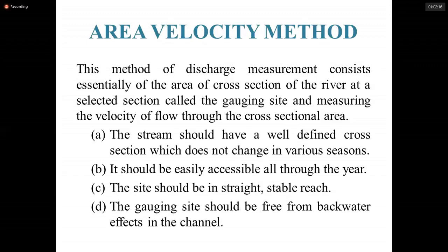And the next one is the site should be in a straight, stable reach. Sometimes the river is not in a straight way, it's going here and there, not a straight line. So we need to select a straight site.